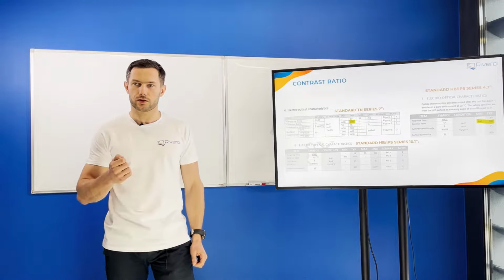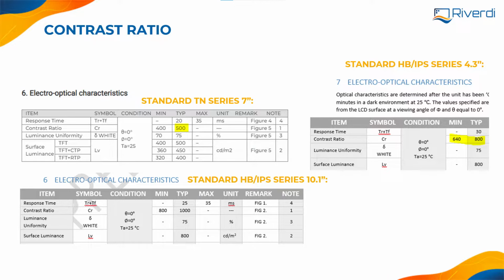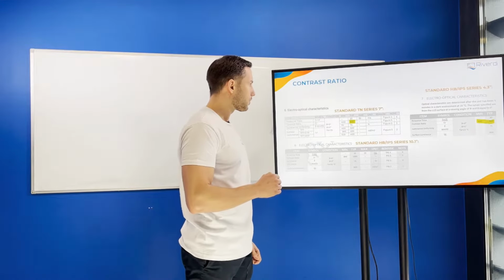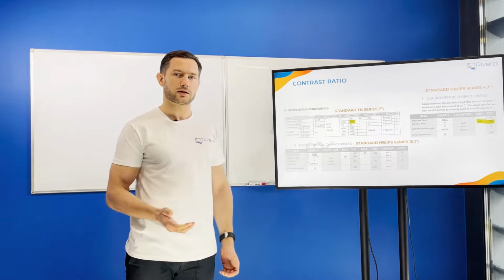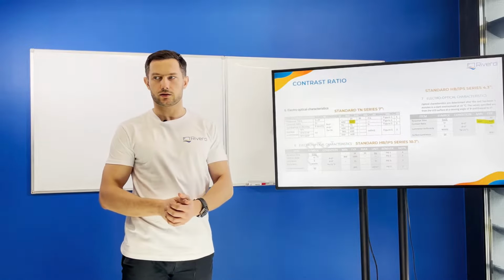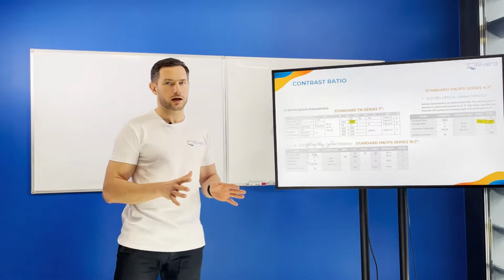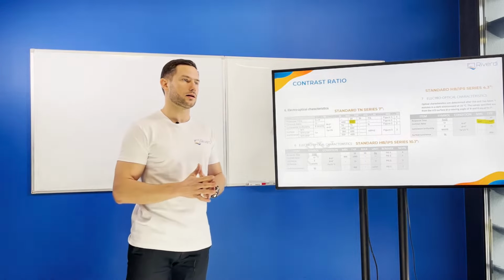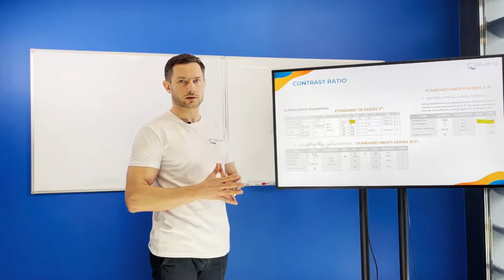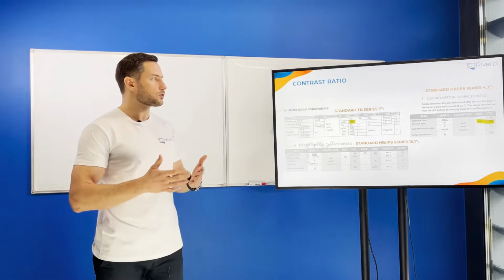It's a parameter that you can find easily in every display datasheet. That is something that we measure in a factory and give, let's say, to the customer as a reference number. The contrast in example datasheets from our datasheets is a couple of hundreds, and I would say this is the standard for industrial type displays. Let's say the low end will be 300 to 500, and the high end will be maybe 1,000 to 2,000 as a value of contrast.